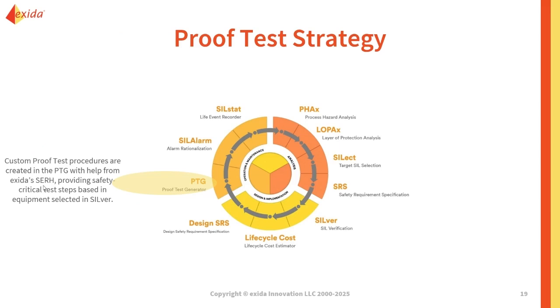Finally, we want to make sure that we have proof test procedures ready to do the proof testing on site. So creating these procedures is important because we know that our proof test coverage is based off of the procedure within the safety manual. So we want to make sure that we're accounting for the steps in those procedures, as well as adding appropriate guidance for the people on site who have to carry out these tests. So you'd want to make sure from a device perspective that you're doing the right procedures, but also make sure that these procedures are comprehensive.